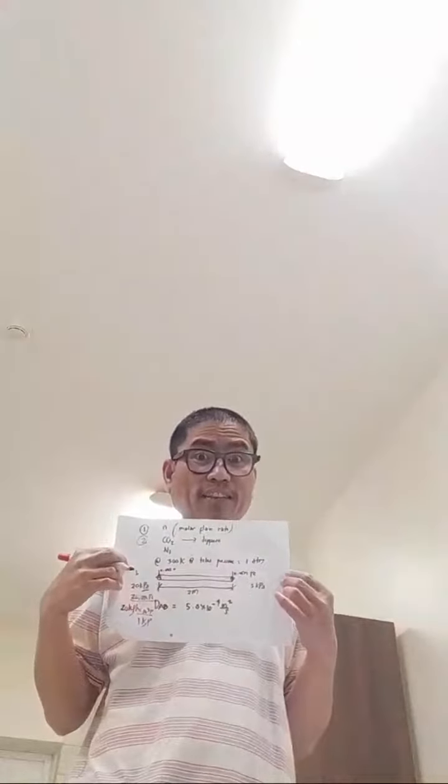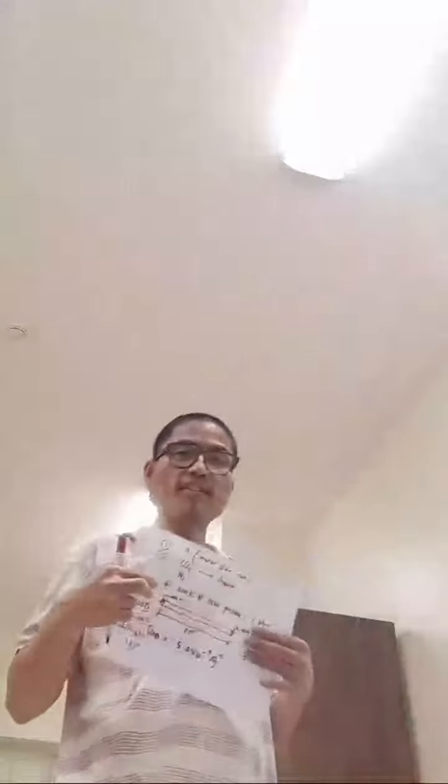And the other one, 5 times 1,000 automatically is 5,000 pascal, right? 5,000 pascal. You subtract first, not with the kilopascal. Why? Because that is not similar with the other units there. The other units that I presented a while ago are not kilo, like Newton and meter squared. So that's a problem. You should break it down to pascal only. So 5,000 minus 20,000, over the length which is 2 meter.